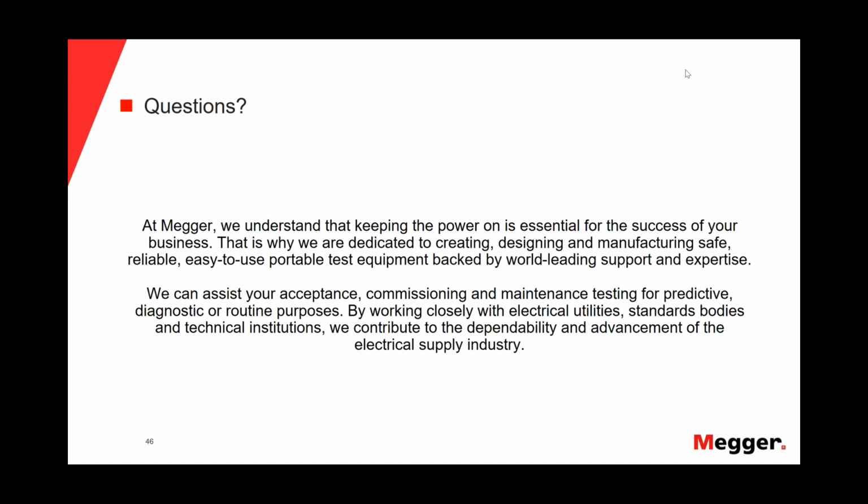So there's two different things. You really cannot compare field testing to factory testing, because you're testing for different purposes. On the one side, you want to make a quality assurance test, which is the factory test, and the other one is you want to see what the actual field condition is, which will be a very different number, because you have all the aging and all the other influences that you experience during the life of the circuit.